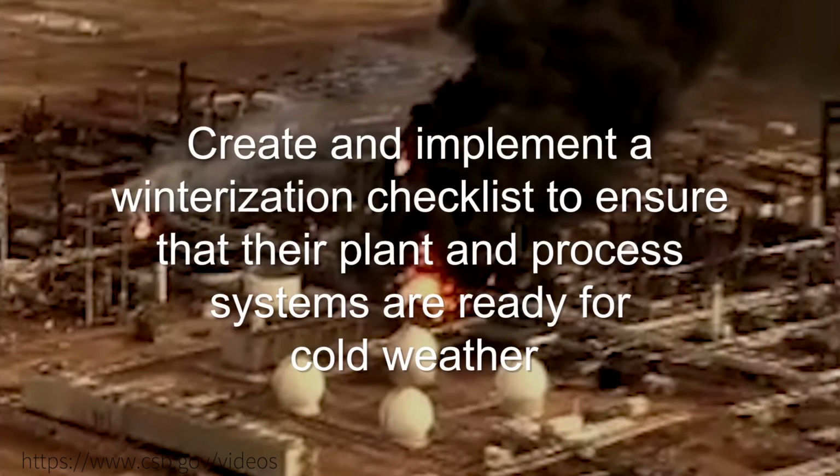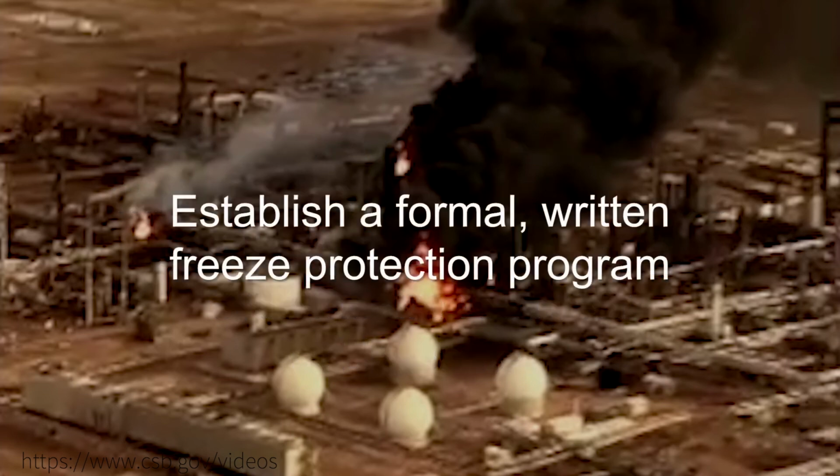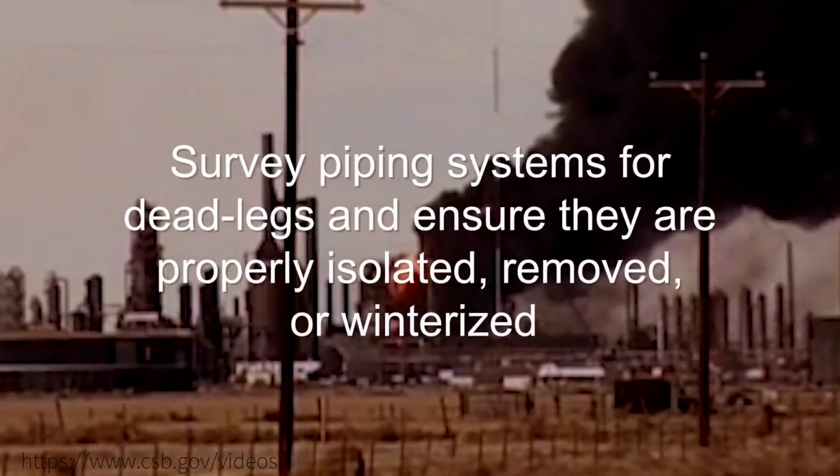Create and implement a winterization checklist to ensure that their plant and process systems are ready for cold weather. Establish a formal written freeze protection program. Survey piping systems for dead legs and ensure they are properly isolated, removed, or winterized.